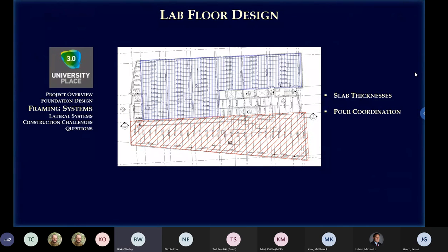The lab design was a little different. Usually for the office space, we decide the slab thickness based on a floor-to-floor fire rating, which for this building was 2 hours. And we used a lightweight concrete mix for the office floor structure. But for the lab floor structure, we were starting to have other ideas.